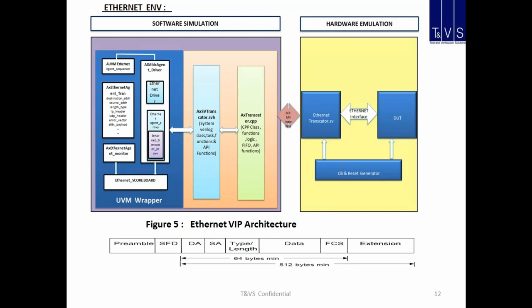No, you can. Because you can have a transactor for the PCIe and a transactor for the Ethernet. You can have a transactor for all of them. So you can put multiple transactors onto the emulator, connect it to the SoC running on the emulator, and then put your software running on the emulator as well.